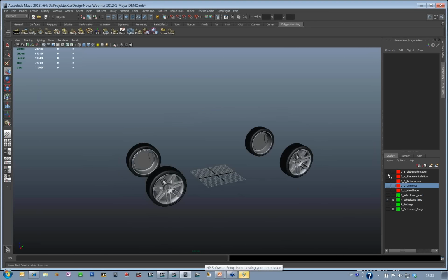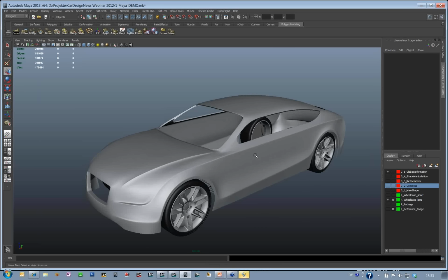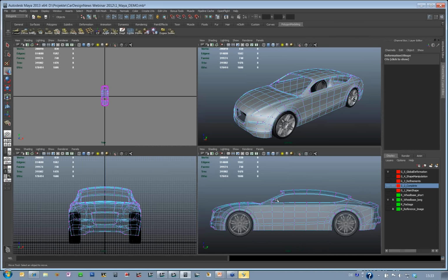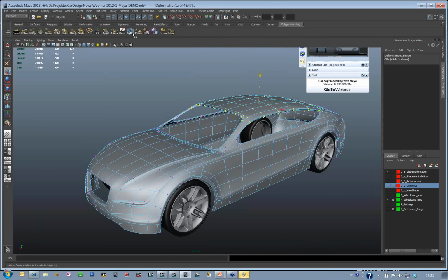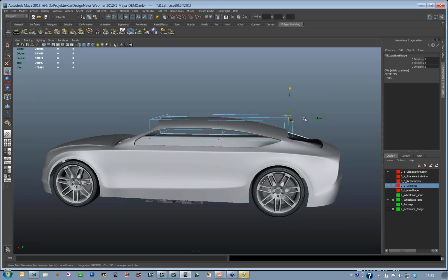Another way to modify geometry is to use so-called global deformers. There's something known from Alias as well. It is a lattice rig, and it works similarly here in Maya. So if I select again a bunch of vertices, I can apply this manipulator on the selected vertices, and at the end I can manipulate very complex geometry with only a few points, these lattice points. So like this. Now I select the lattice points and start to move them. I hope you see it well. So like this.